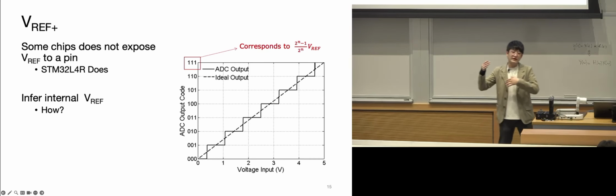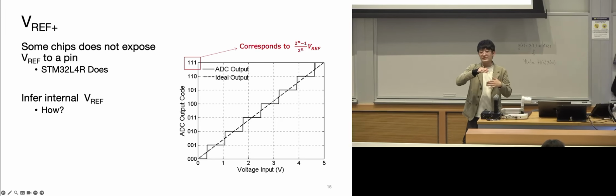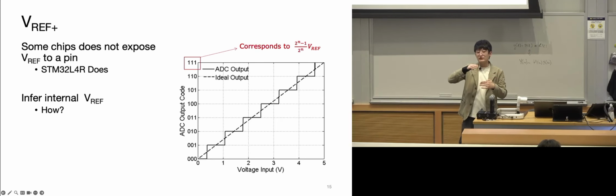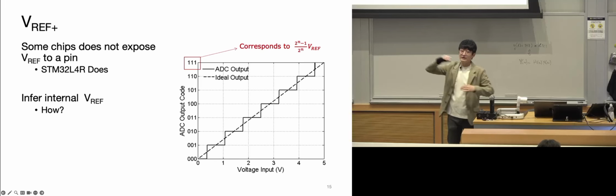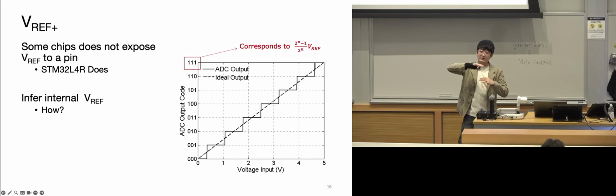Then that goes to an ADC channel, say a 10-bit ADC channel, that ranges from 0 to 3.3 volt, which is the VCC being used for the V reference. That will give you a really optimized range of your ADC bits. The 10-bit value will mostly all be used, so you essentially have a higher resolution signal, right?